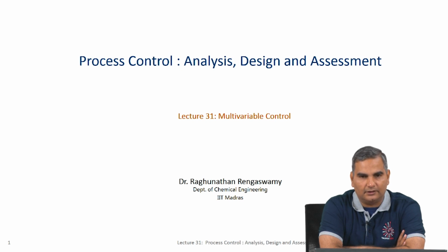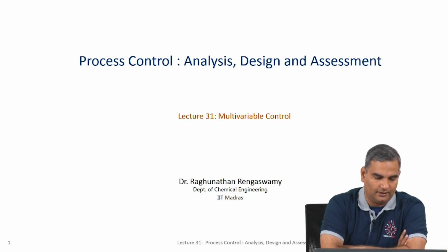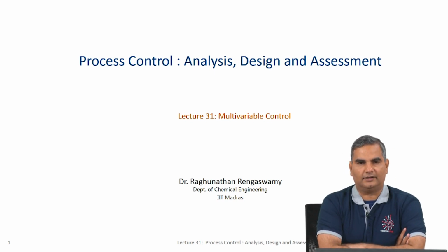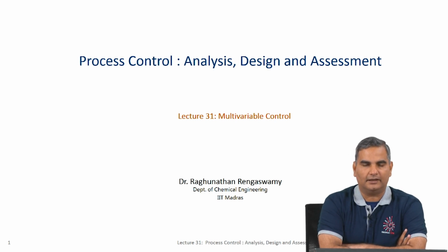So, in this lecture I am going to introduce this idea of relative gain array, which is used to do this pairing. So, you could basically do this pairing and then think about all the other techniques that we have discussed and described in detail till now. In the last lecture on decoupling, we looked at the transfer functions between these various inputs and outputs and then directly used those transfer functions in deriving these decoupling matrices.